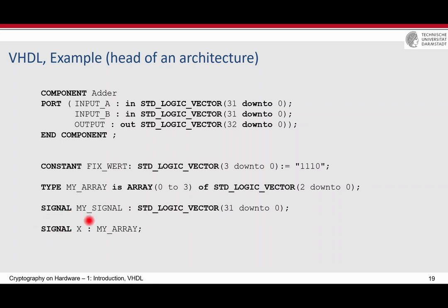Or you select or define a signal, say x is of my array. Yeah, means that x now is an array from 0 to 3, and each element of the array is a std_logic_vector of 3 bits.